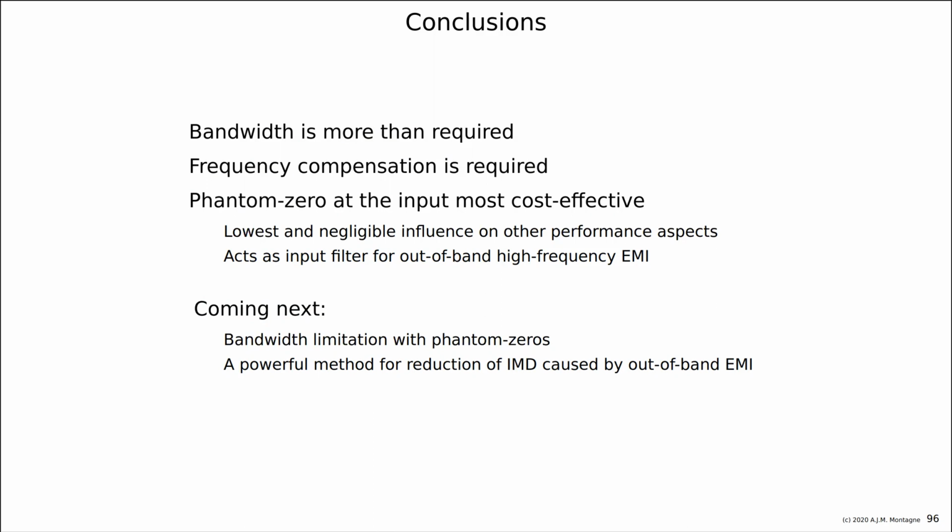We have seen, by the way, a few lectures back, the unity gain voltage follower with a CS stage, that we called a common drain stage or the source follower. There was attenuation in the loop, and there was a low loop gain. But there we have used phantom zero compensation. And maybe now you understand better if you go back to that lecture. I think the video is already uploaded. If you go back to that lecture, you will also appreciate more the effect of the phantom zero.